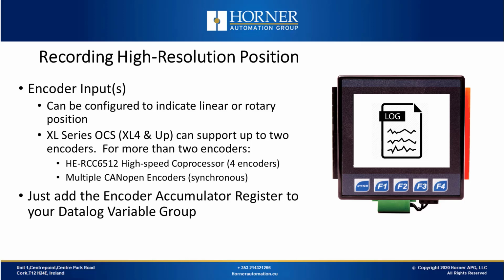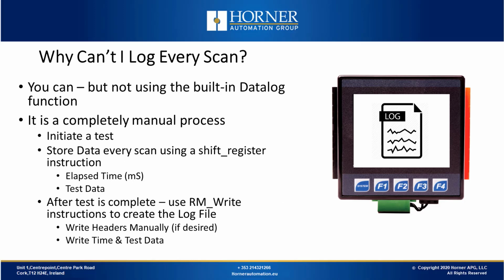If you need more than 2 encoders, we have a RCC6512 high-speed coprocessor that can support up to 4 encoders. And we've had plenty of customers utilize CANopen-based encoders that are synchronous. You can add the encoder accumulation register to your data log variable group.